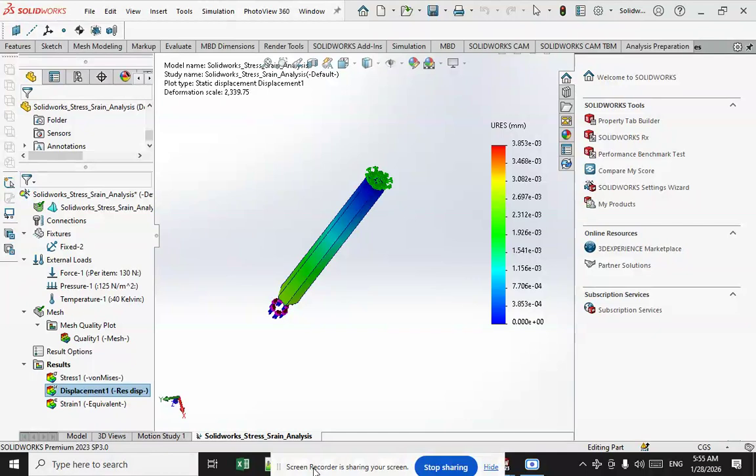Built-in stress or preload. A preloaded structure is one that has internal forces, stresses, and strains imposed within it by various means prior to application of externally applied forces. For example, a structure may have cables that are tightened, causing forces to develop in the structure before any other loads are applied. Tempered glass is a commonly found example of a preloaded structure that has tensile forces and stresses that act in the central plane of the glass, which causes compression forces to act on the external surfaces of the glass.